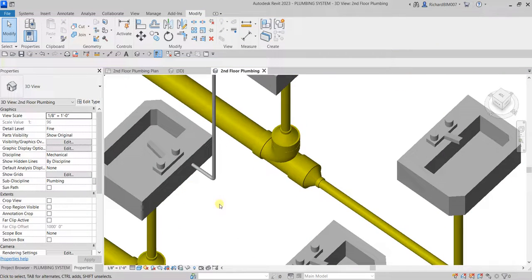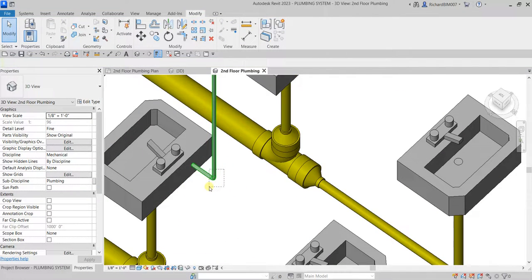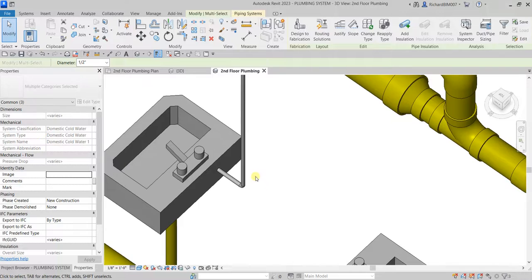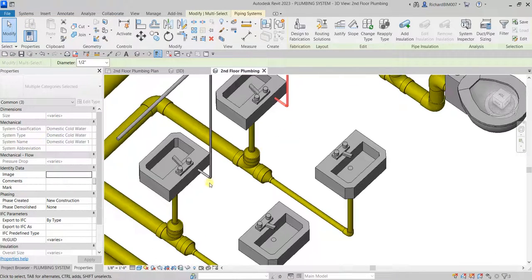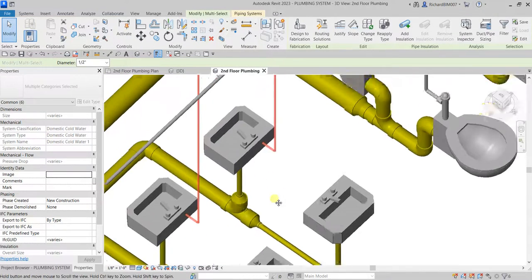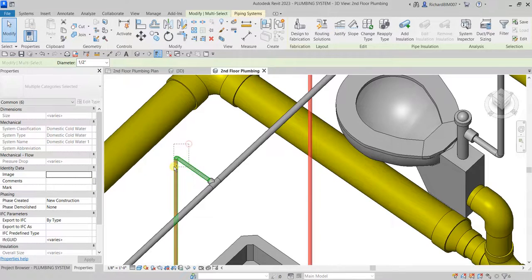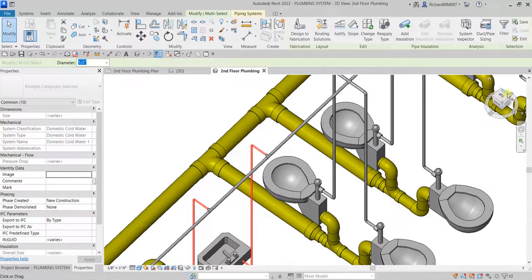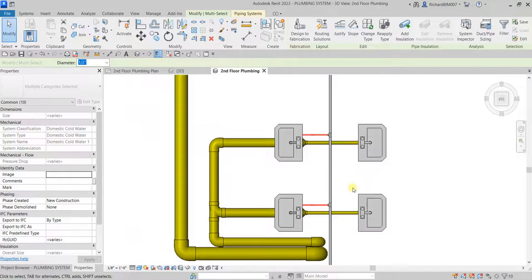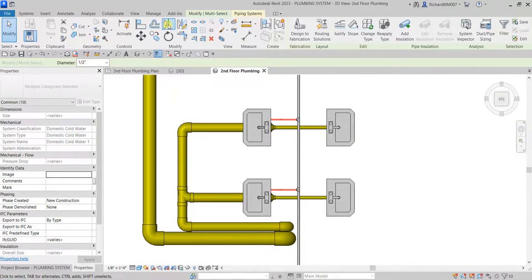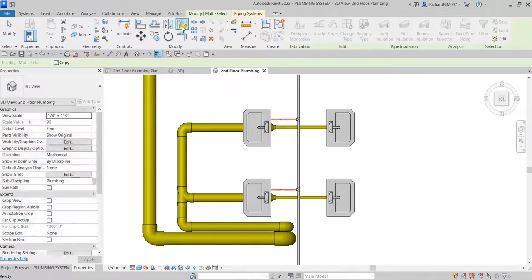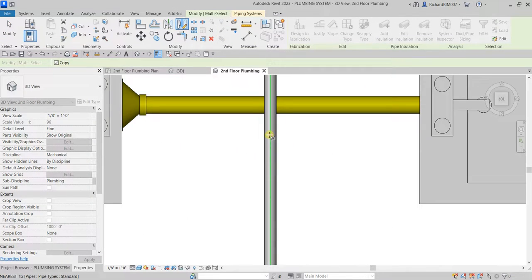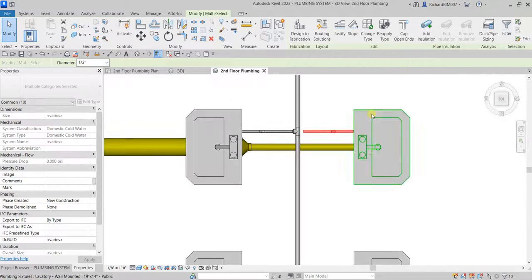Okay, I'm gonna show you another tool. So let's use mirror. Let's select that. Oh, sorry, you need to hold control. There you go. And then hold control, select, hold control, select. Okay, and then let's go to the top view again. We're going to mirror this. So let's click mirror, draw axis, click that one. Click this here, 1, 2, boom.